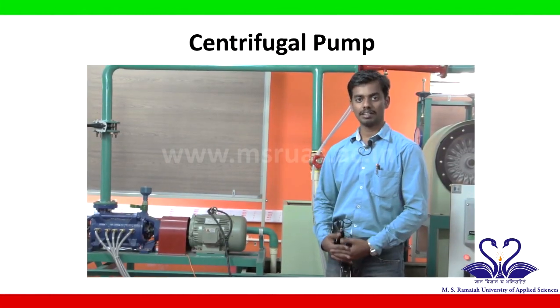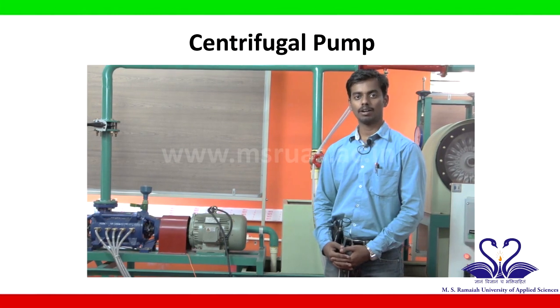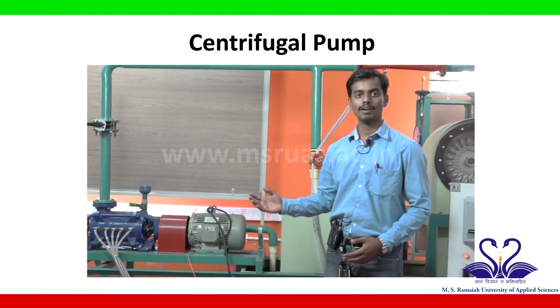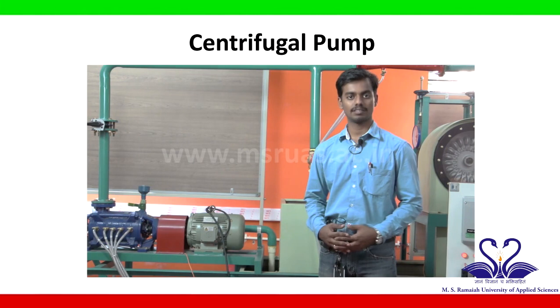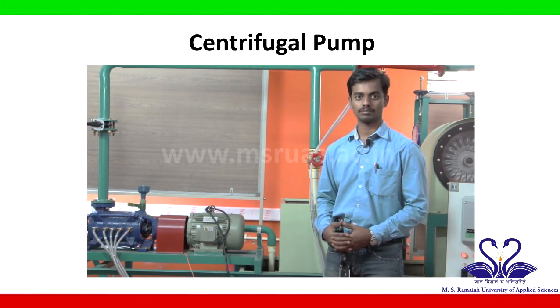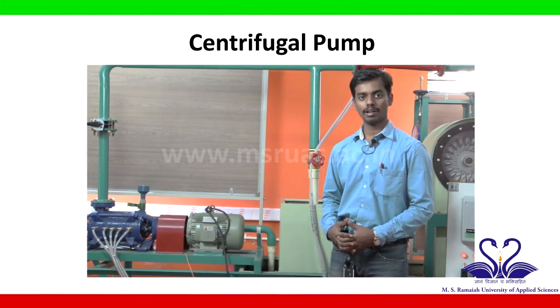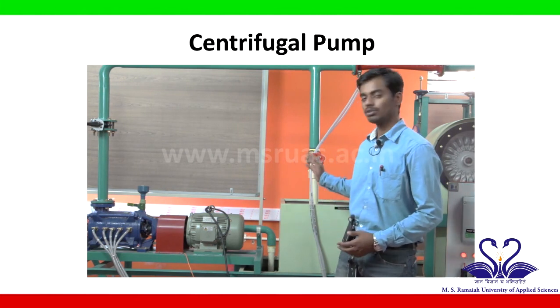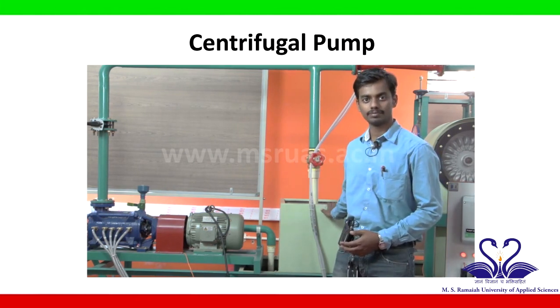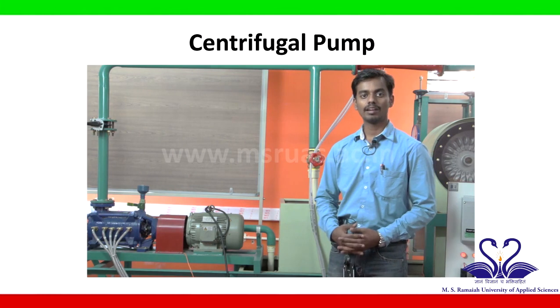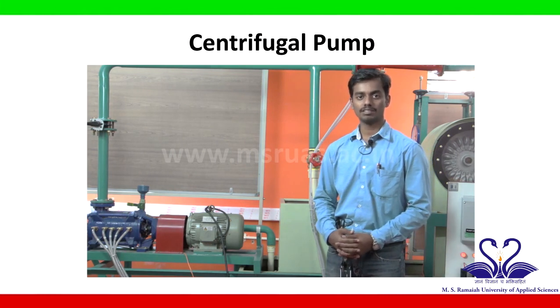More trials can be taken by closing the discharge valve and noting down the different heads available at the discharge. Also, the corresponding actual discharge should be calculated. By doing so, we can calculate the pump efficiency and also the overall efficiency.